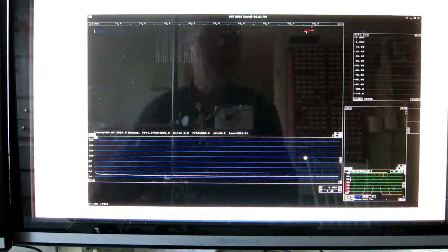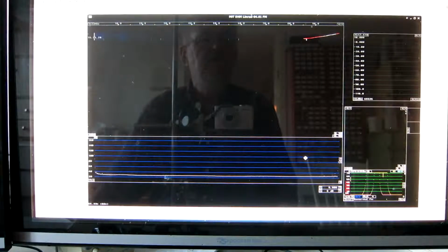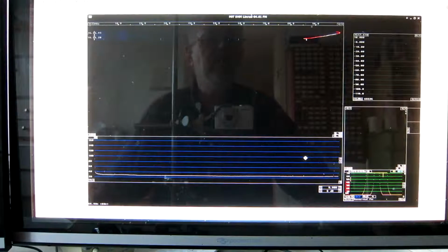This is to show the aliasing. The hardware is a PCIe 9842, and there is a preamplifier in front of it, but there is no filter. So it's only the anti-aliasing filter of the card itself. And you can see here the aliasing comes back.